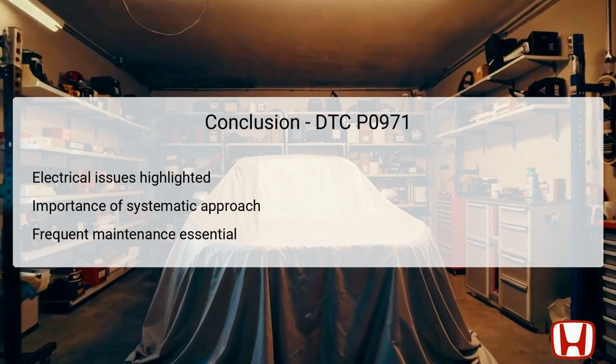The verified steps laid out involve verifying the DTC, testing critical components, checking continuity of wiring, and measuring resistance values. Lastly, frequent preventive maintenance can significantly reduce the risk of recurrence, maintaining optimal performance of the vehicle's transmission system. By understanding the complexity of these systems and following the recommended guidelines, owners can enjoy a smoother driving experience while prolonging their vehicle's lifespan.